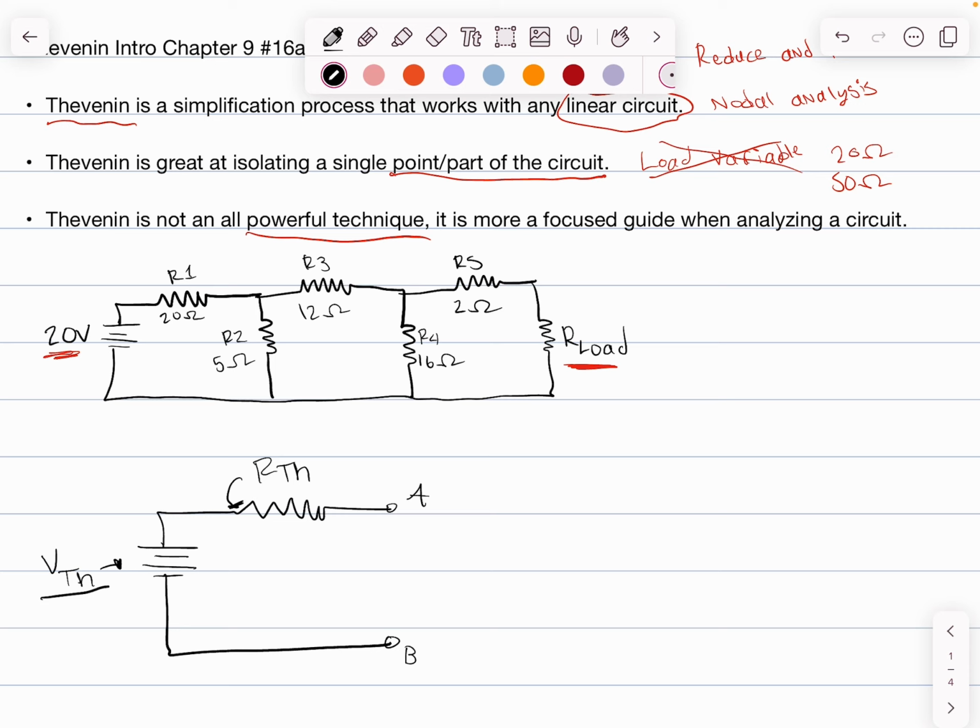We want to go from a more complicated circuit like this top part and get to one circuit with one voltage source and one resistor in series. If the question asks further, at the end is where we would connect our load and then go off based off values off that. In this case, since they're not going to ask any questions on our load, we know our final answer should look like this.